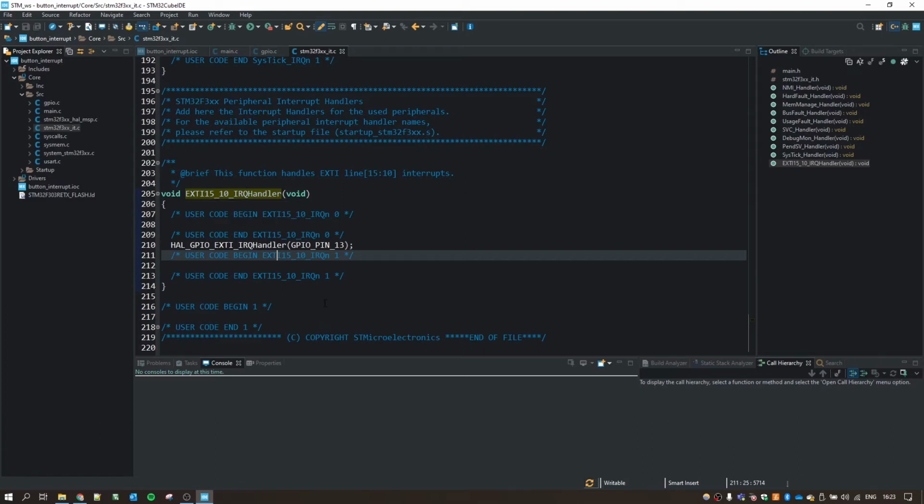Because, well, we don't have any UART set up at the moment, and neither do you have any printfs, and we don't even know if the LED blinking will work. Now the easiest and the fastest and the quickest way to do that is to just double click over here and set up a breakpoint. So I'm just going to set up a particular breakpoint.